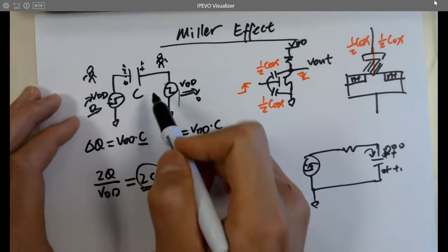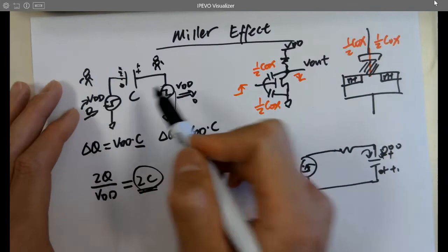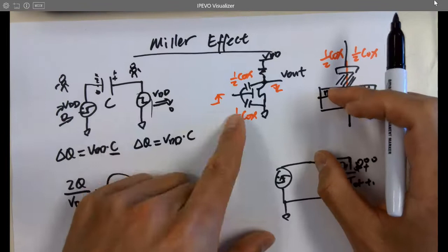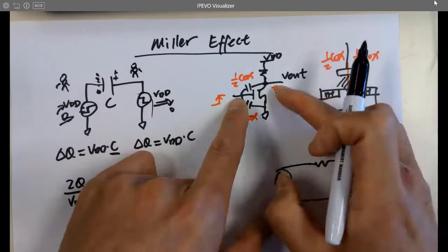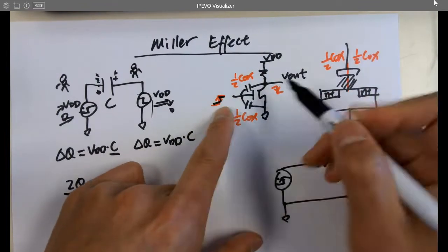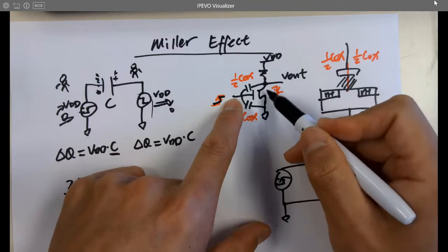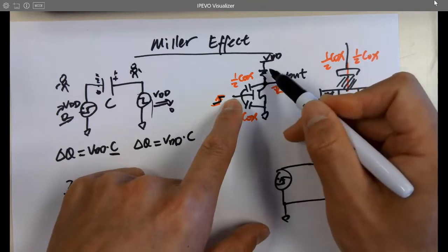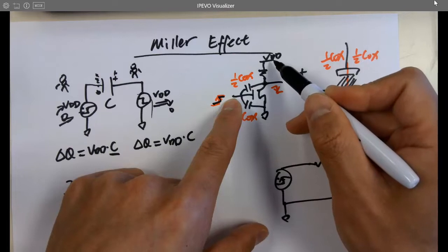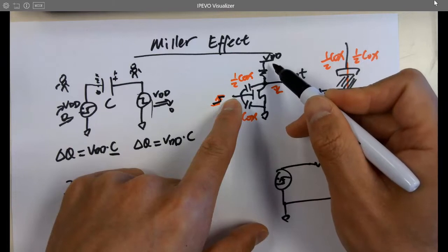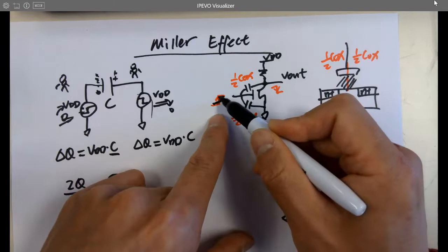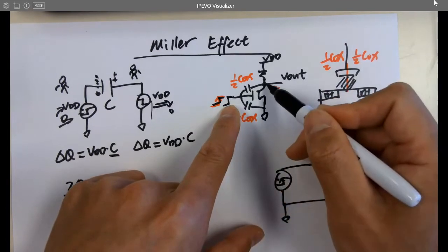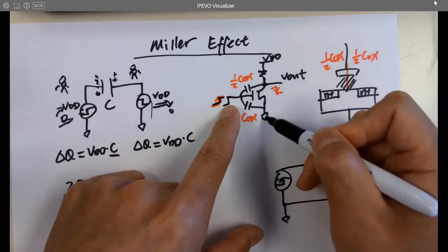We modeled that circuit in this way because for the NMOS, exactly the similar thing happens here, right? When you open it up, the channel is opened up, so it's discharging this part from VDD. You got a resistor limiting, so it's not shorting ground to VDD. This charges from 0 to 1, and this becomes 1 to 0 because it opens up the channel and pulls it down to ground.